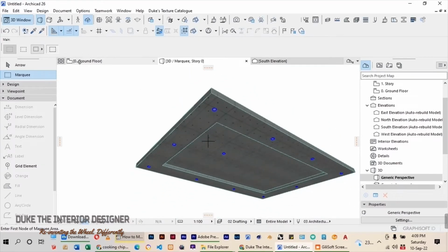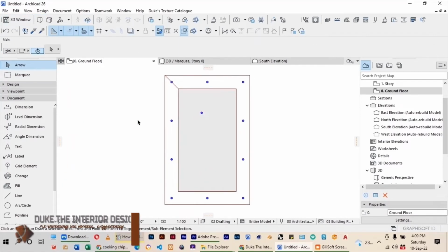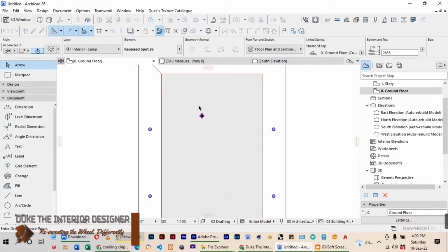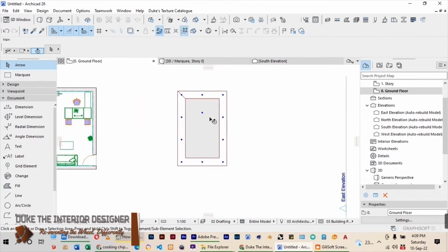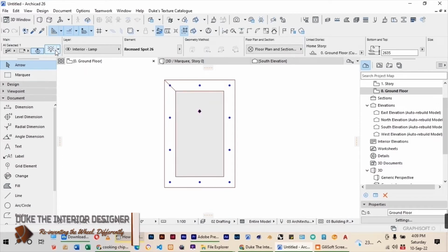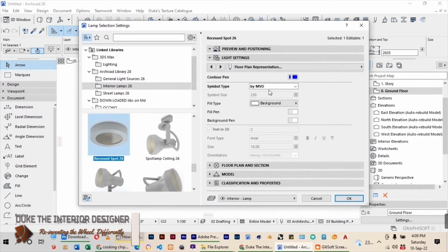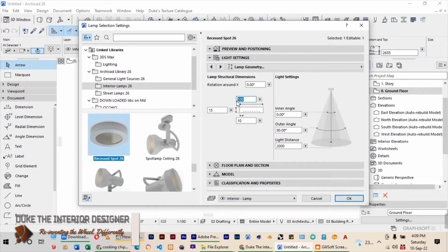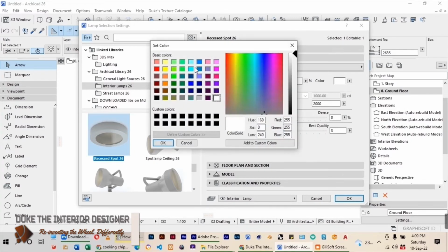Then in the middle, we can do spotlights. We can align this to the mid one. I need to do 3 spotlights, so I'll click on this, go to settings, spotlights. We don't need them big, can do 70. Again, the rating is okay. We can do warm light. Maybe I'll do yellow.